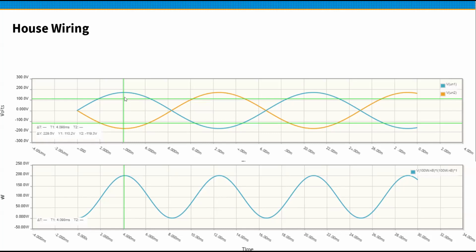See, what did I plot? It looks like you're doing 2-phase. Yeah, that's your 120 volt in, which is going up to about 170 volts. This is 100 and 200. So the peak to peak is going to be what was it, 270? Close to 300 volts. Oh yeah, this is the other phase.